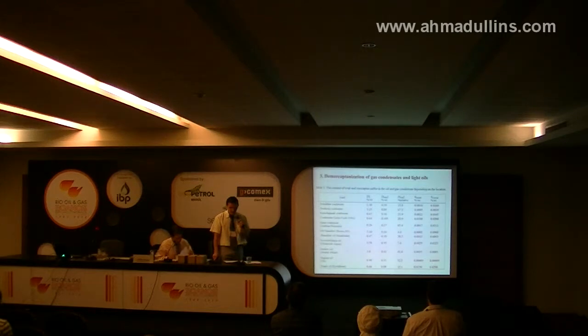This scheme is attractive in terms of removing mercaptans, which cause intense corrosion of equipment in the heating zones due to the mercaptans' low threshold of thermostability, from 140 to 170 degrees Celsius.